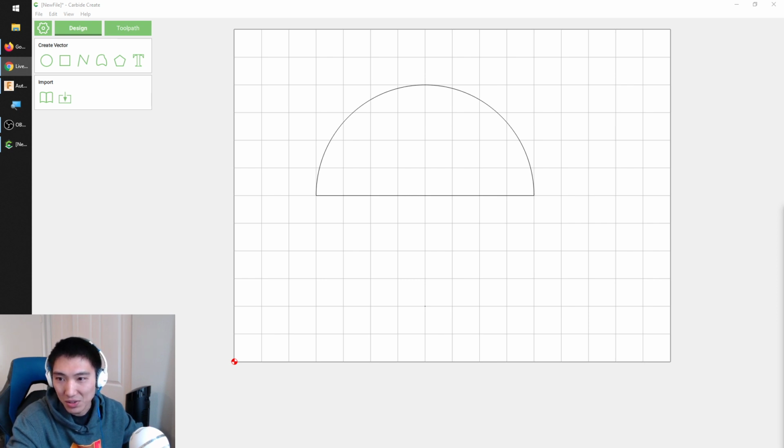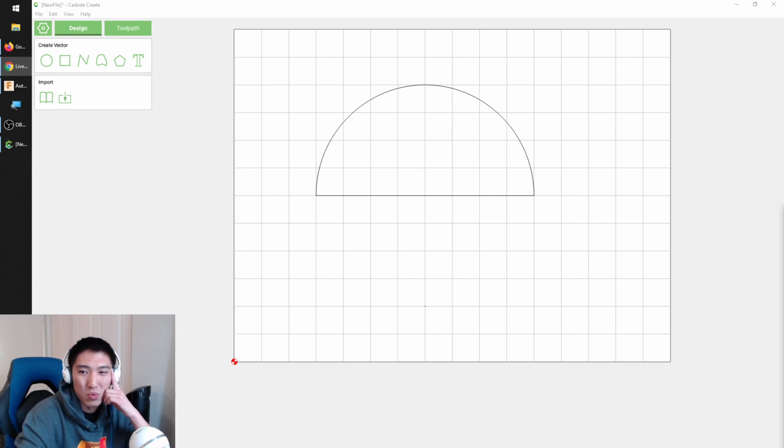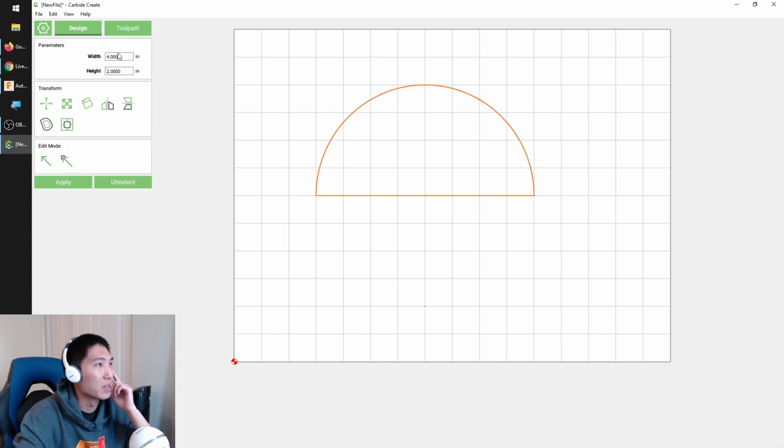Complete CNC novice, you can cut softwood with a PCB engraver for about 1mm engravers. It really just depends on picking speeds and feeds that'll work. So you can start with our speeds and feeds if you want to engrave.